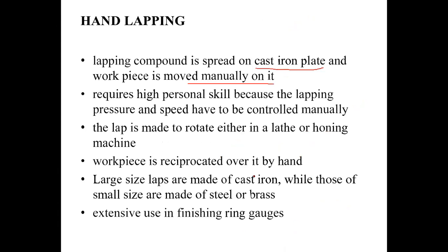Manually, this normally happens because you are working with very small workpieces. Small workpieces you can hold in the hand and just rub. This is similar to the process you have done in your MMT in metrology. One student just now remembered emery paper. Same thing, this is a kind of emery paper. In emery paper, the sharp particles stick to the paper. In lapping, the sharp particles do not stick to the paper, they are simply placed on the surface.